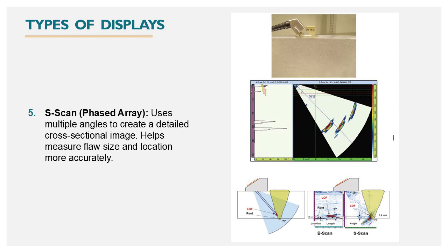The image is a cross-sectional view of the area where the ultrasound passes through. Location and size information can be measured for any reflectors that are in the sectorial scan. Phased array ultrasonics accomplishes this by using a transducer that contains multiple elements, 8 to 128 commonly, that are excited at intervals to create constructive interference in the wavefront of ultrasonic energy.